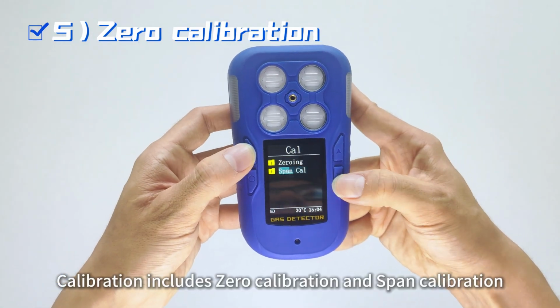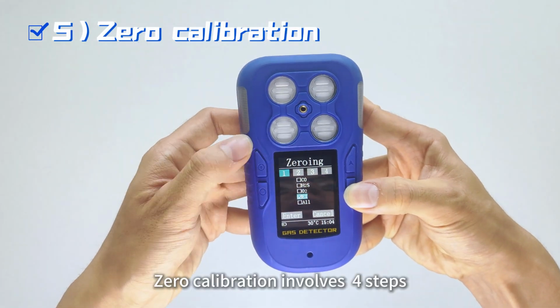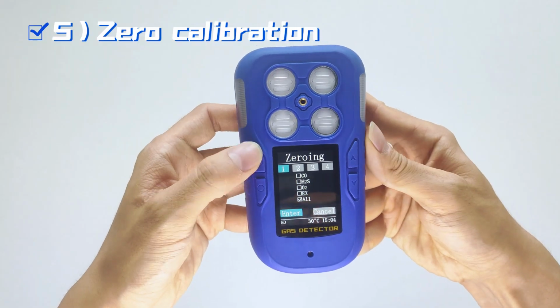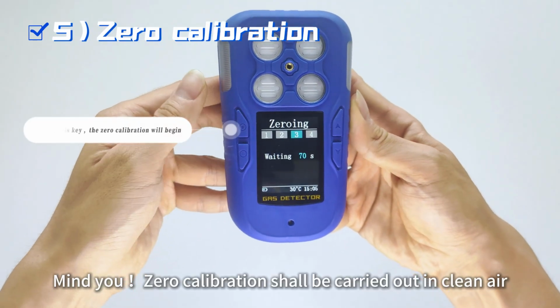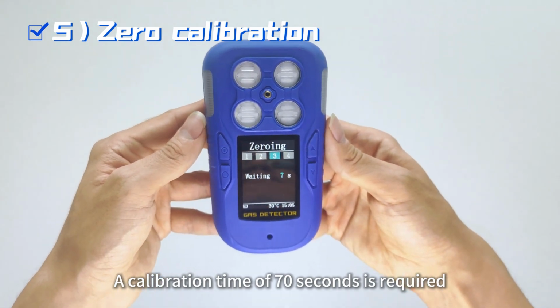Calibration includes zero calibration and span calibration. Zero calibration involves 4 steps. You can calibrate a single sensor or several sensors at the same time by ticking them off. Mind you, zero calibration shall be carried out in clean air.